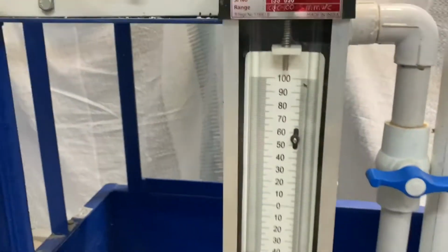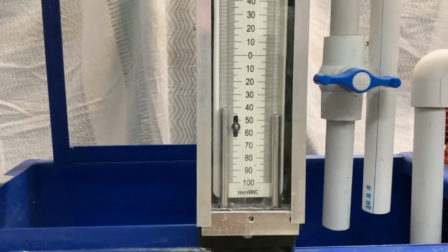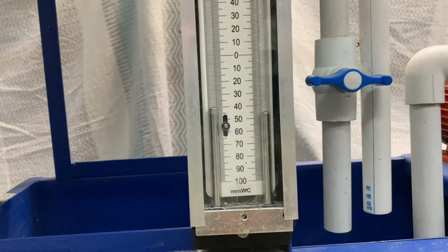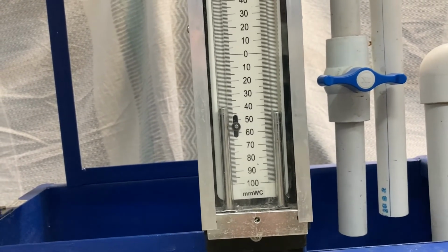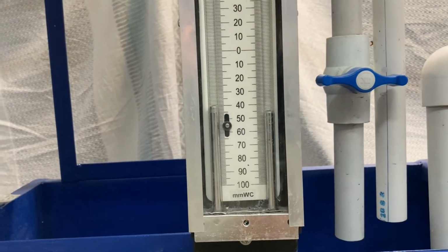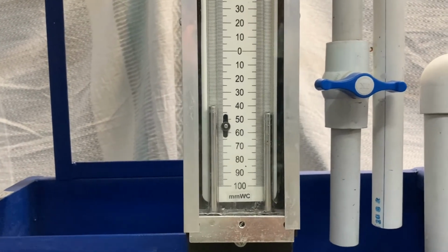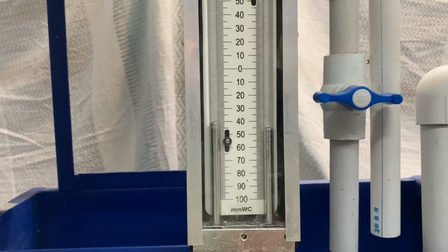So now take a look at the manometer readings at this point of time. As we can see clearly, there is some static error here, so we need to keep this in mind, because for all the subsequent manometric calculations we need to subtract this reading.